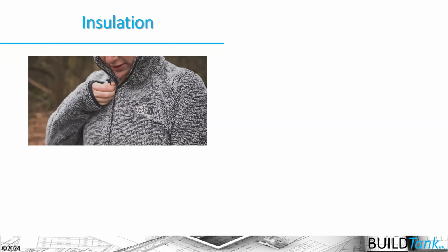The objective of those insulation materials against our body is to trap a pocket of air. So we understand that it's the pocket of air that is resisting the heat flow from higher concentrations to lower concentrations, not the material. The objective of the material is to trap that pocket of air, and the pocket of air is what's giving us that R value.